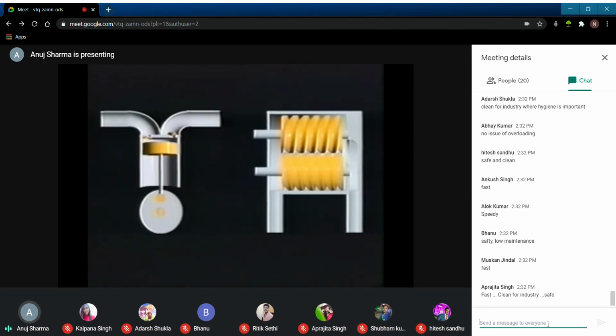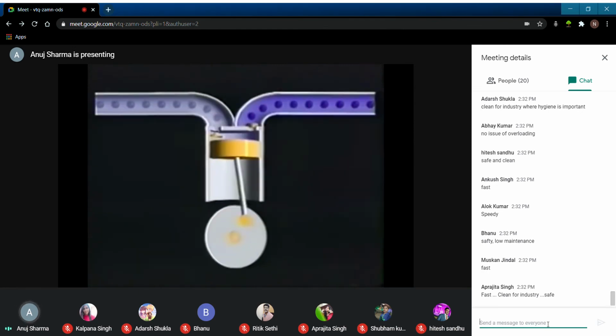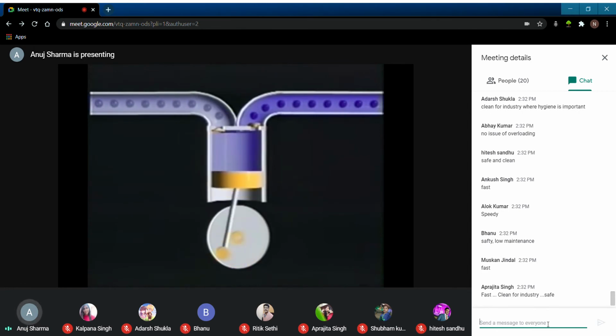The drawing on the left represents a reciprocating piston compressor. When the piston moves down, it draws air into the cylinder. It then moves up, compressing the air. Compressors that contain one cylinder are called single-stage compressors. Each stroke of the piston produces a burst of compressed air.